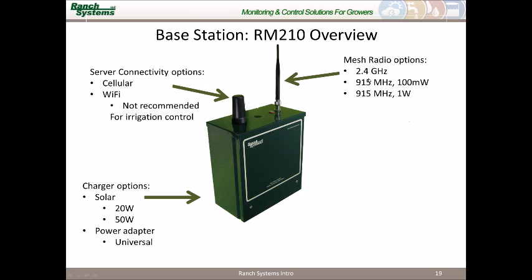And then you have a variety of options for the radios. Basically, these just depend on the terrain and the distances that you would like to cover. So from the top down is the order in which the signal is propagated, and we have our best one here, which is the 915 megahertz 1 watt. Substantially more expensive, but really great range and can work in areas where there's lots of canopy and hills, for example.